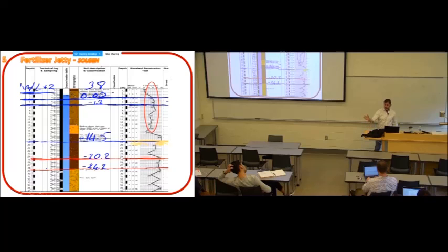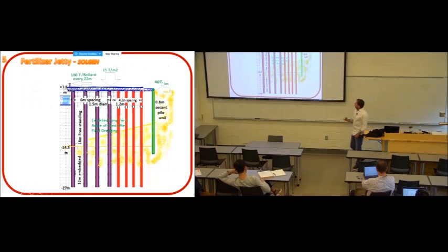You remember the formula, cNc plus qNq plus 1/2 gamma B N gamma, which by the way is a wrong formula, but we used it for so many years with many correction factors. So some geometry here, and the loads. Look at the loads. You have 100 ton per bollard. The bollard is where you tie the boat. There is one bollard every 22 meters. You have 15 ton per square meter, that's a lot of spread load, and 40 ton per linear meter coming from the earth pressure.